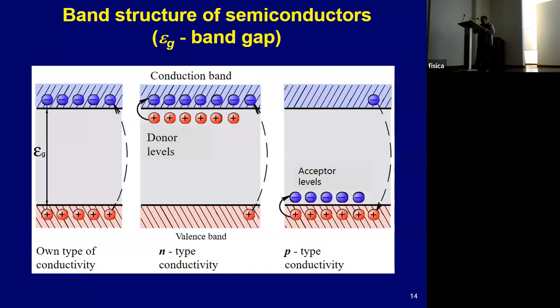But we have to solve this problem. In order to use a semiconductor as an ionizing radiation detector, it is necessary to create a layer depleted in charge carriers. It can be electrons or holes. Then the ionizing particles, passing through this layer, form electron-hole pairs in it by analogy with the ionization chamber. Under the action of an external electric field, charge carriers reach the electrodes, which is recorded by a current pulse.